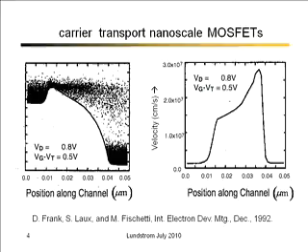So you can see a lot of electrons in the source. You can see them going over a barrier and flowing across the channel. You can see that they're sort of going quasi-ballistically. A few of them scatter and lose energy, but most of them go to the drain without losing a lot of energy. And you can see on the right the average velocity of those electrons versus position.